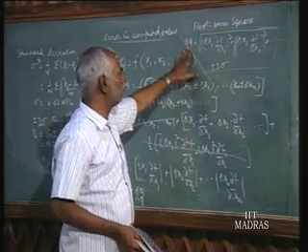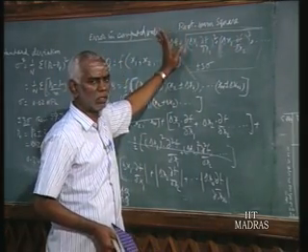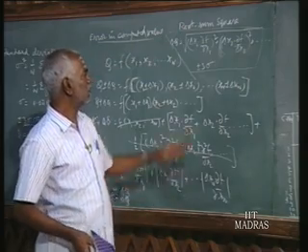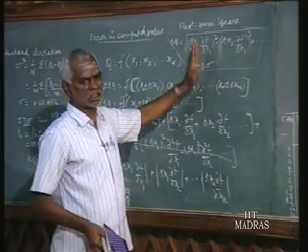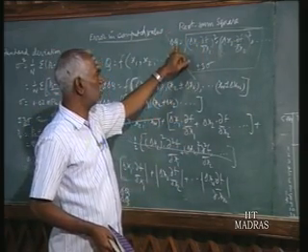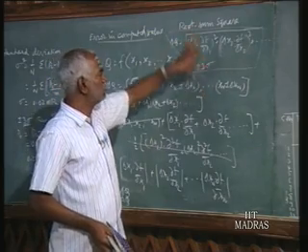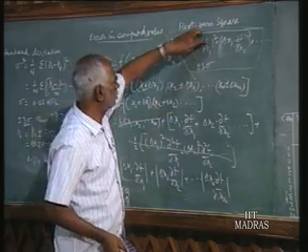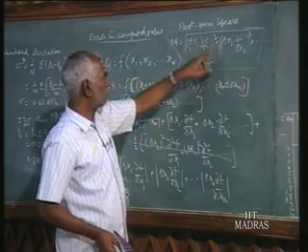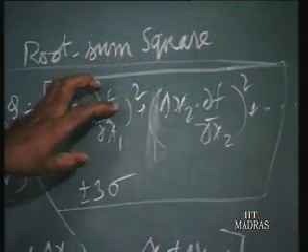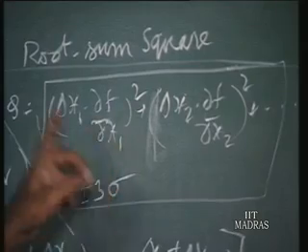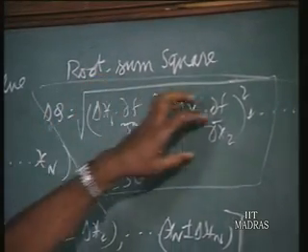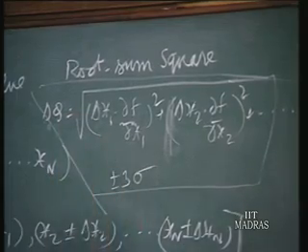If that is given, then based upon the error in the computed value we have to select the individual instruments. There are infinite procedures to obtain it, but we will follow one method: we say the component of error contributed by each measurement is equal, that is, the part contributed by the first instrument towards delta q. We assume the component of each instrument is the same.